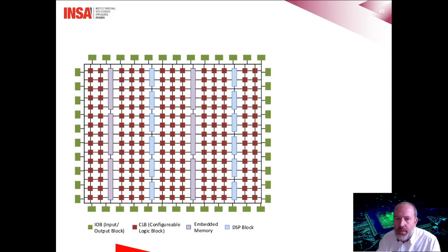The figure you see here shows the building blocks of an FPGA. It shows the logic cells arranged in a matrix, here in red, all the squares in red. There are also embedded memories arranged in columns, in purple here, which are generally available in the form of large blocks pre-mapped in silicon, and which allow implementing a larger amount of memory in addition to the small logic cells.